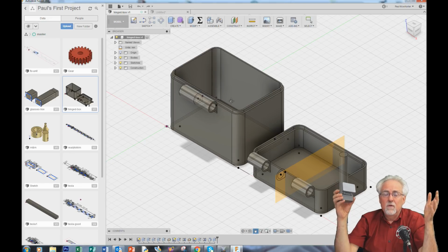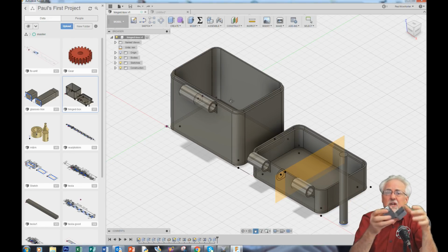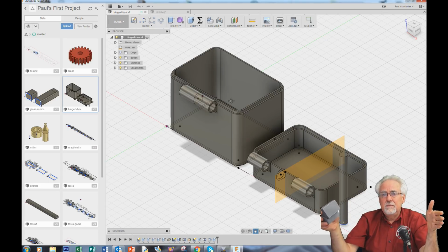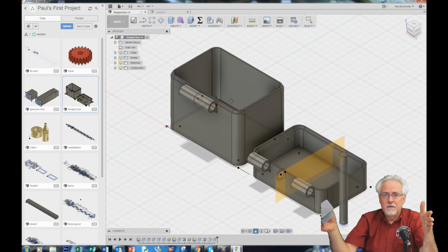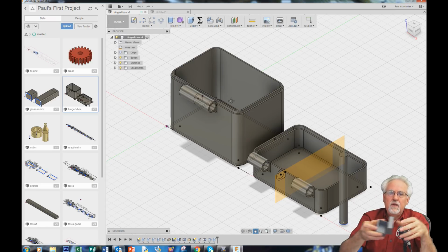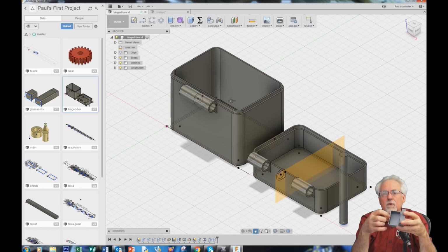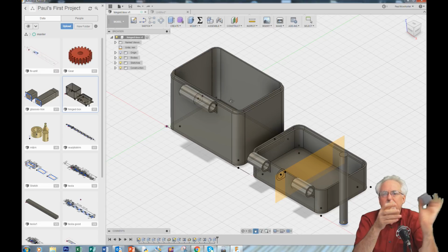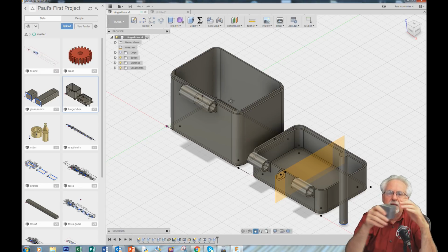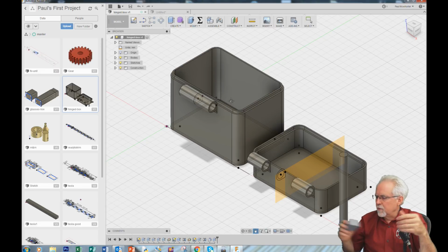Now, if you think wall thickness and lip thickness, you might want any different wall thickness, but is lip thickness dependent or independent? Would you have any old wall thickness and any old lip thickness? No. You would want the lip thickness to always be half of the wall thickness. Why? That way it's always going to close and fit together. What other parameters are you going to need?